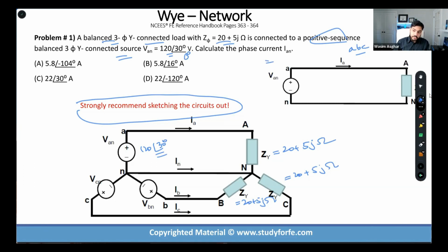One of the things that I like to hammer on and on in the live training, especially when we're doing 3-phase circuits, is that we should always try to convert everything into YY. In fact, if there's one takeaway from the entire live training session, and we have detailed discussion because I do 3-phase, per unit, and symmetrical components over the same weekend, with a lot of overlap between them, it's that whenever you're dealing with 3-phase systems, bring them into a YY system. Why? What's the reason I'm so hell-bent on converting everything into a YY?